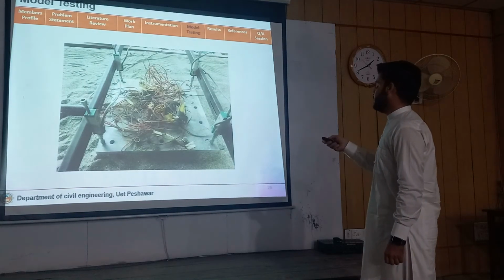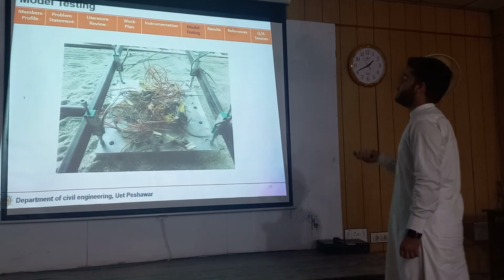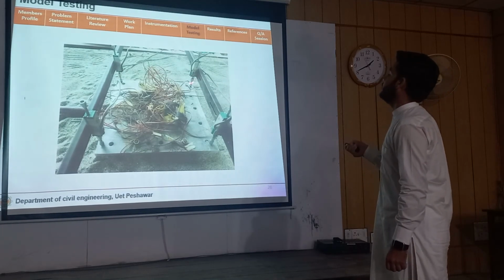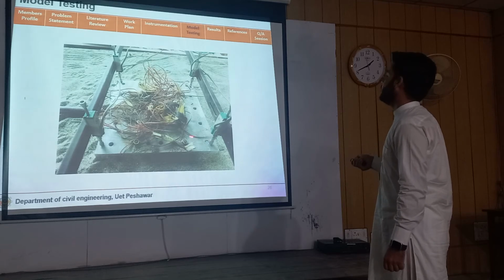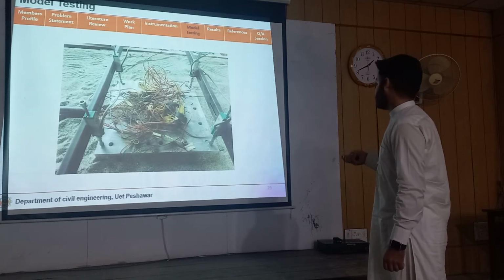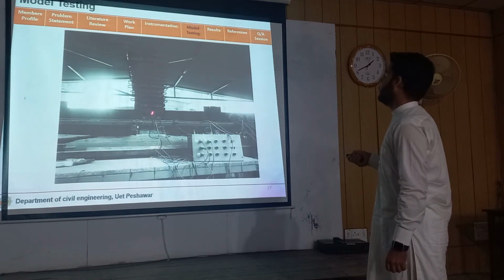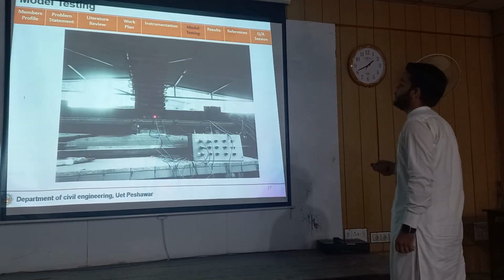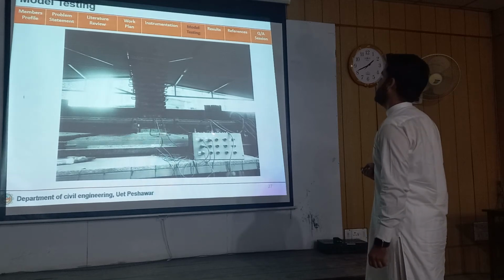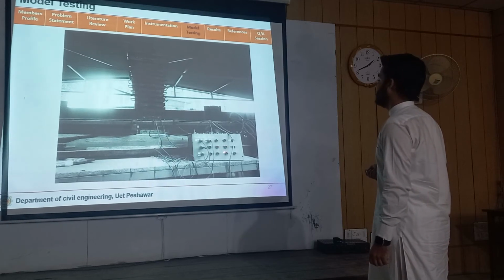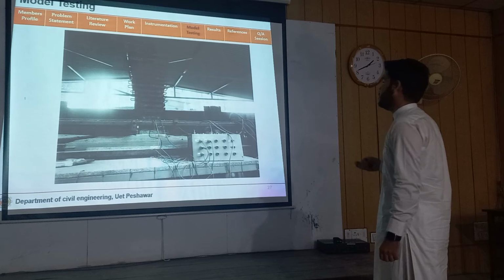So this is the picture of how we performed the test. These are the LVDTs. 4 LVDTs were connected at each corner. This is the pile raft. These were the loads. We placed them one by one at an increment of 16 kgs, and this was the data logger, which in turn was connected with the software. So this was all from my side.